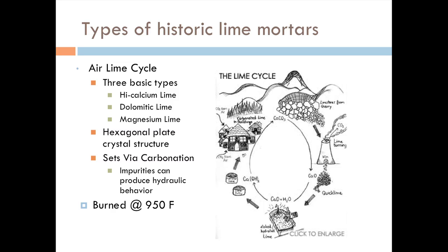So going back to that essential key component, lime, that's been around for 3,000 years, there's three basic types. You have a high calcium limestone, which is mainly composed of about 90 to 100% calcium carbonate, which is the shells and marine life and sediment that's been compressed into a stone under the ocean floor for thousands of years. It's very pure. It's used in all types of chemical processes today, whether it be in steel manufacturing, water treatment, and also in mortars.